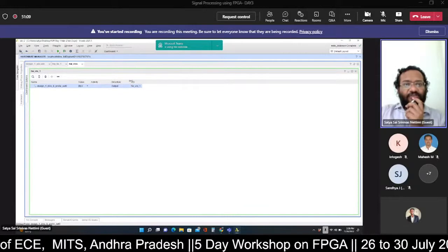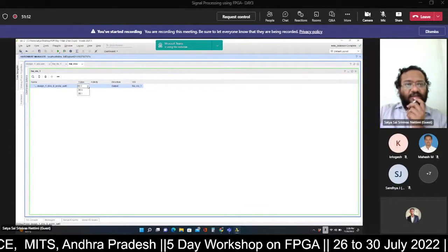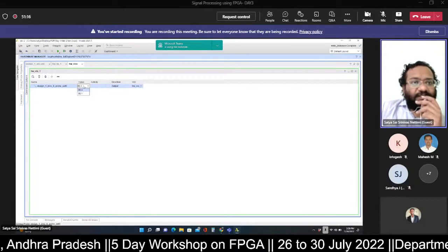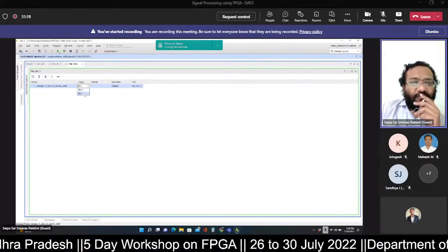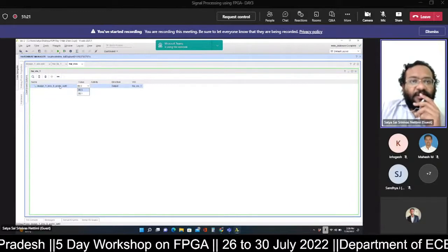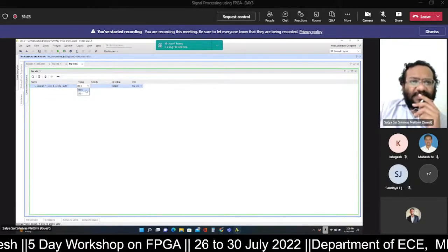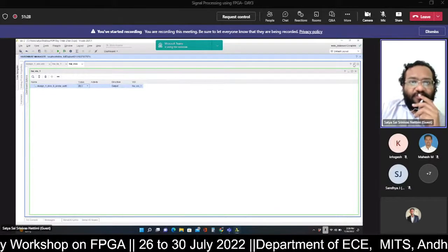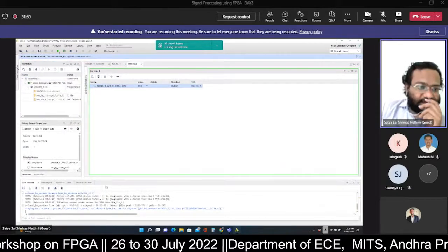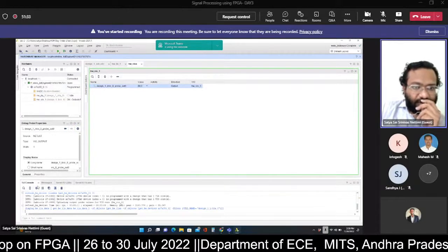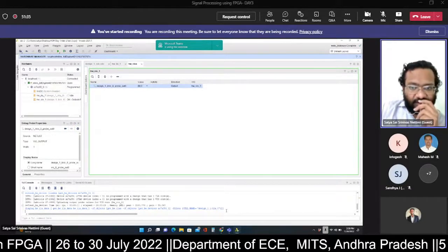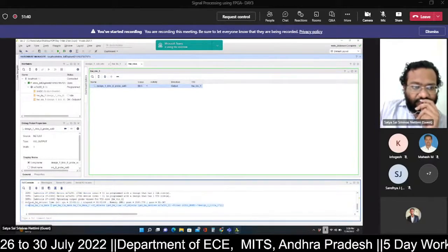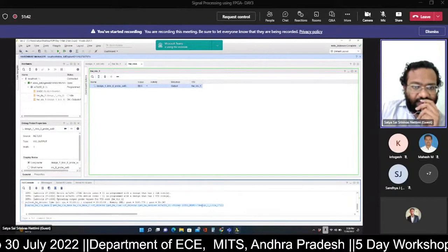Now the probe is added. Here you get a drop down menu. You can provide the value of this probe as binary 0 or binary 1 since this probe is a single bit. By default, let us first give a binary 0. So the 0 is fed. How do you know that the 0 is fed? You just minimize it and in the Tcl console at the bottom, you can see a blue command. This is the indication that we gave a value 0.